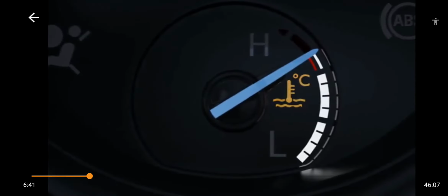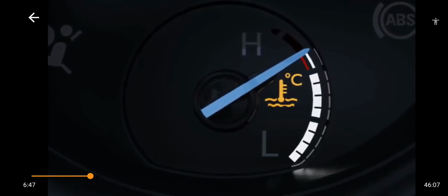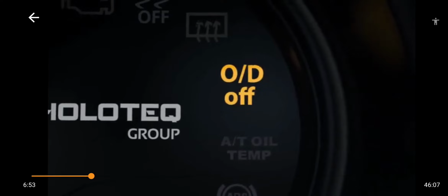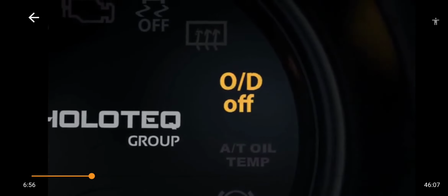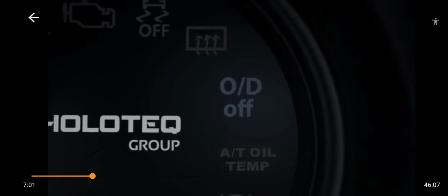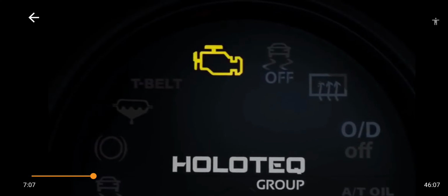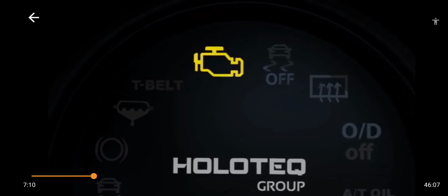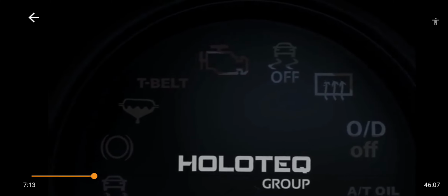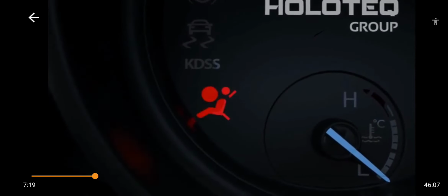Engine temperature rise indicator. Stop driving and turn the engine off immediately. OD off indicator. The use of OD reduces the fuel consumption. Engine fault indicator. Go to the repair workshop and link it to the computer to indicate the fault. Airbag system SRS warning indicator. It indicates the existence of a fault in SRS.